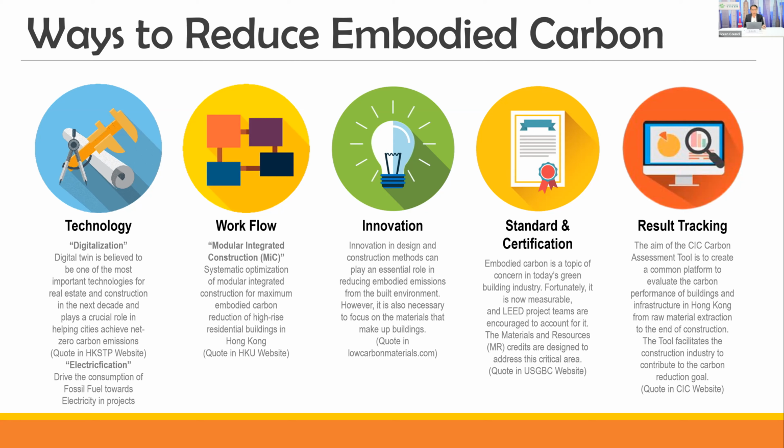And compliance with green standards or green certificates is one of the important parts that can reduce the embodied carbon. If it is a green building, we can join green building certificates such as BEAM Plus, LEED, or China Green Building labels. If it is a material, there are some material certificate schemes like the CIC Green Product Scheme. After all, you have to track your results to see if your embodied carbon is on track.